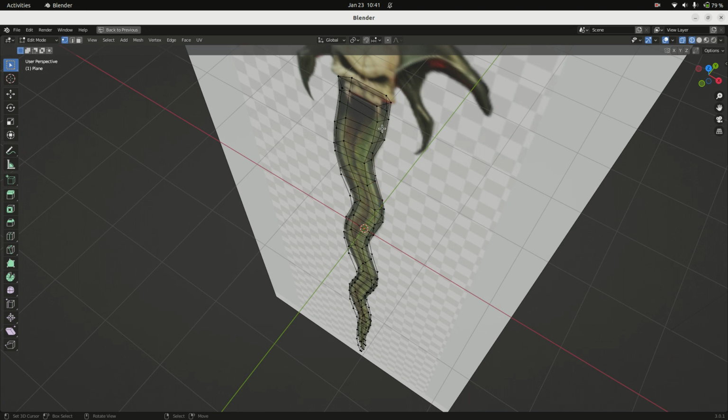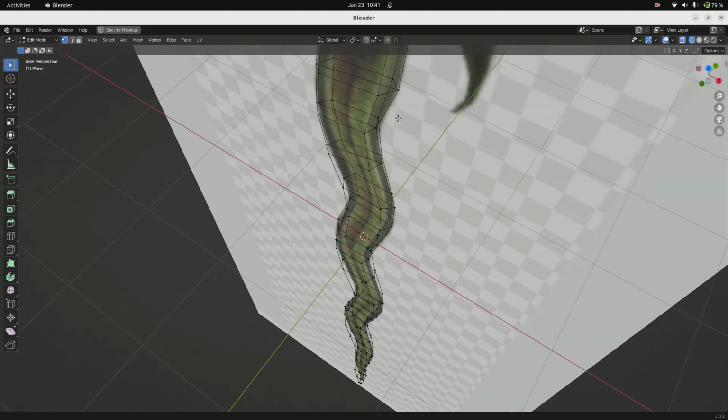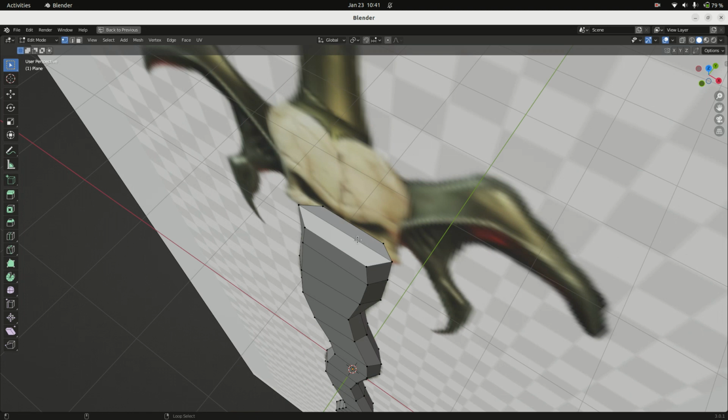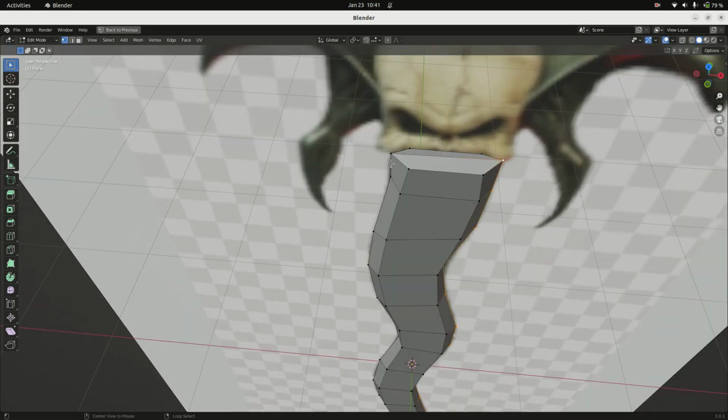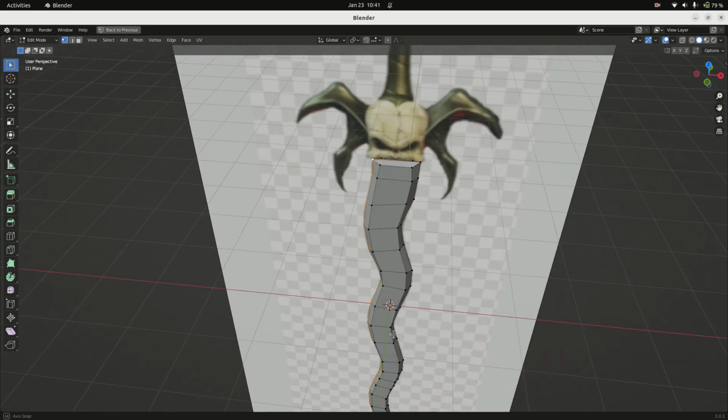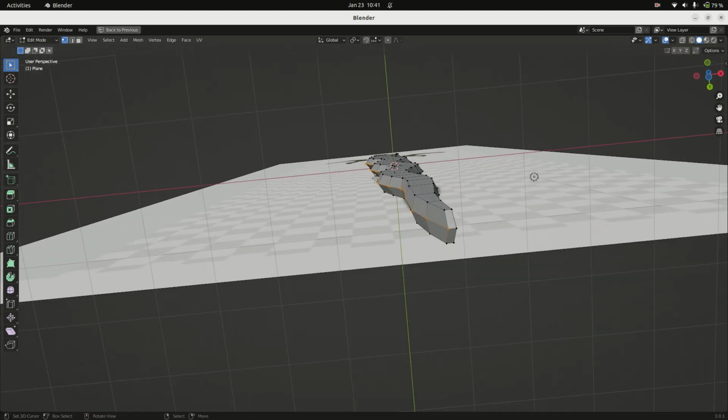So I just showed you loop cut. Now I'd like to show you loop select. Make sure I have the view here. There we are. Let me see what that command is. So if you hold Alt and select, you'll be able to select an entire loop of edges, or a continuous line of edges.